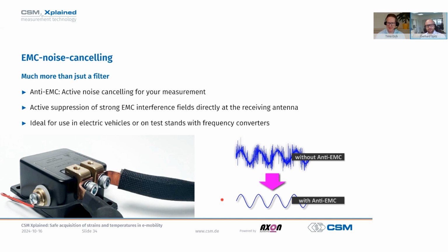So they record the surrounding and subtract the surrounding from your mixed signal. And this is what we do, but not on acoustic. We do this on electromagnetic field. And we developed this together with some large OEMs when they started to test their own electric cars. And this is a really successful result of this research, our EMC noise cancelling system. Yeah, that's really, really good.